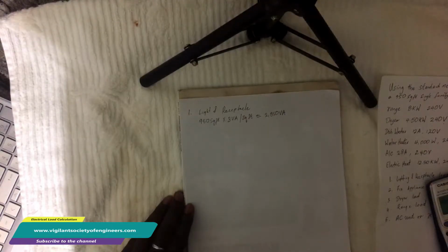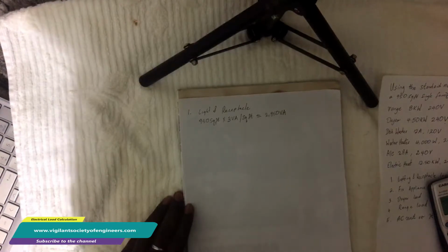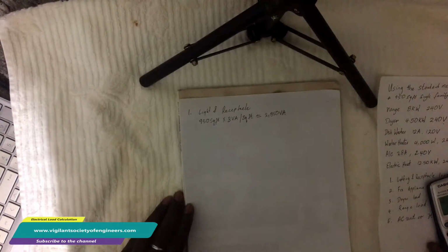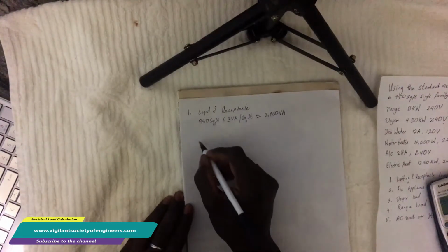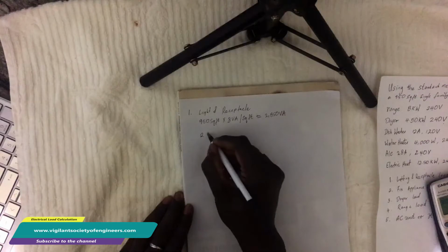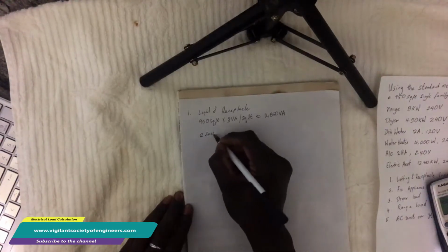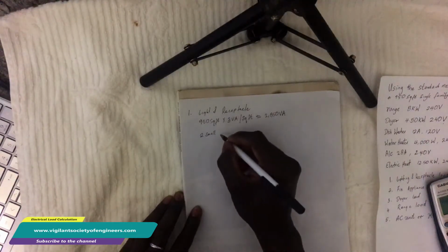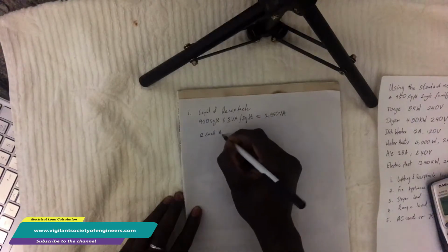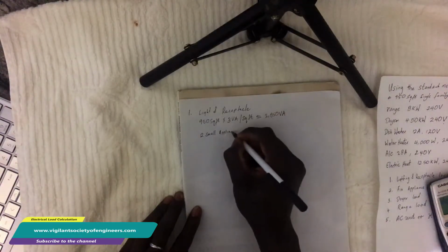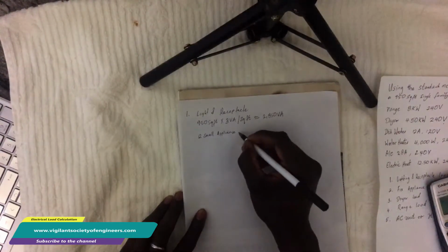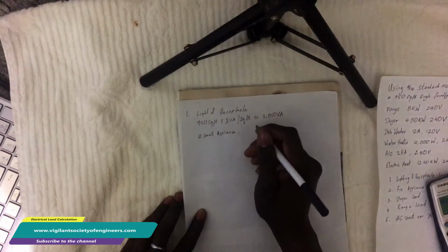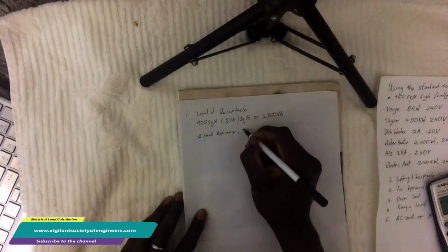All right, and the next is a receptacle load, and that is based upon the small appliance and also the laundry appliance. All right, so standard, we must have 2 small appliance circuits, both at 1500, so that gives you 3000 VA.